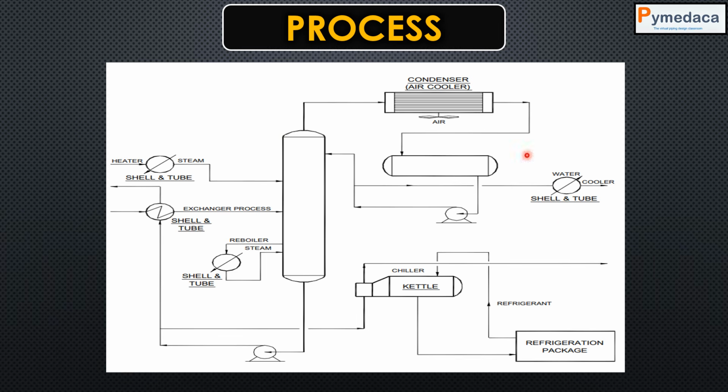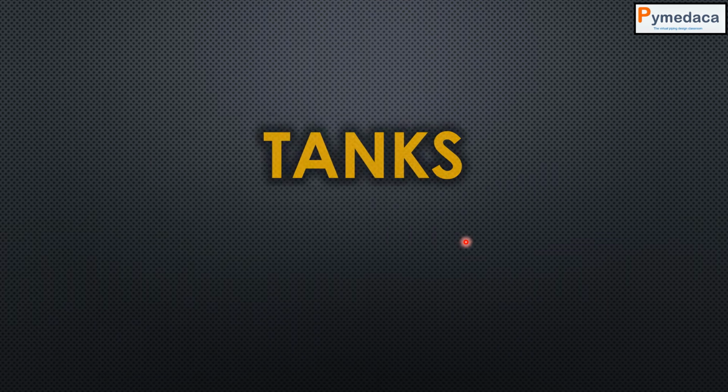See, if you look at the P&ID, let me show you this example over here. See, this is the equipment which is used as a drum in the P&ID. Fine. So from here, the services from the air coolers go to the equipments, and from here it is again pumped to the major pressure vessels. We can call them distillation columns or any other columns. So drums are used as an intermediate storage to transfer a fluid from one major equipment to another major equipment. So this is how we need to have a conceptual understanding.